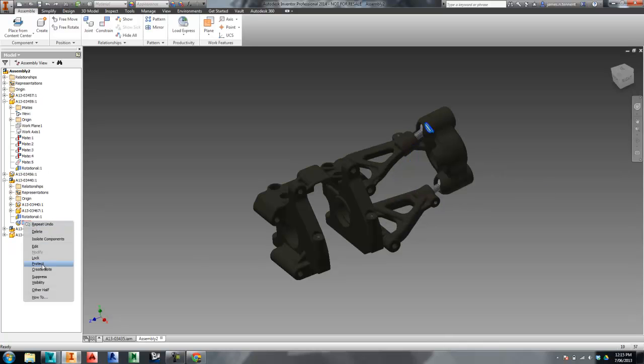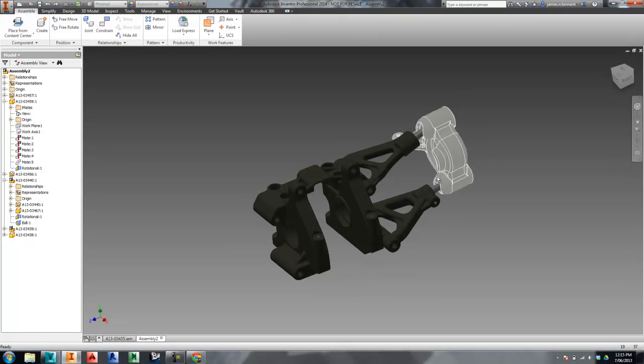You've also got this protect section, which just says, well, this is a high priority constraint. If I try and use another constraint which is going to conflict with that, basically it's just not going to allow it. It's a protected constraint. So that's also pretty cool.